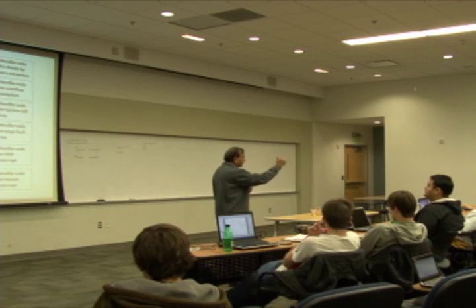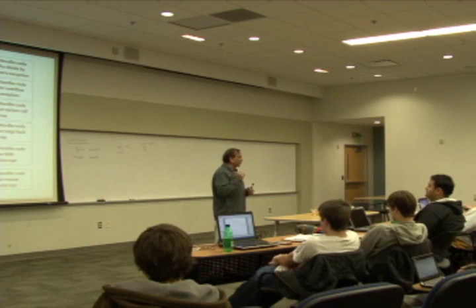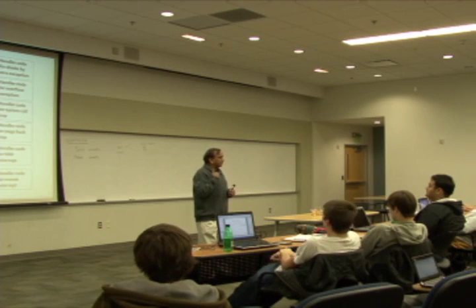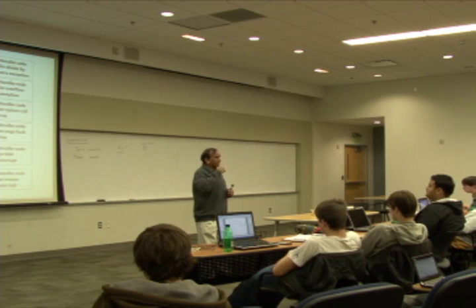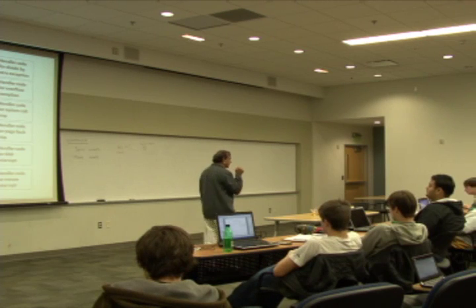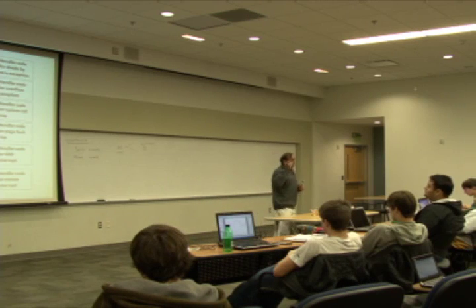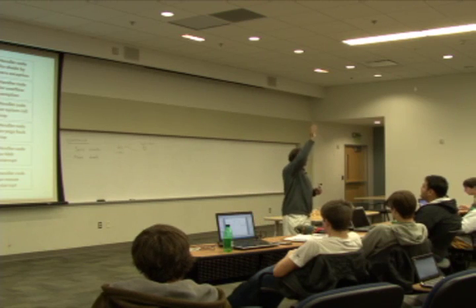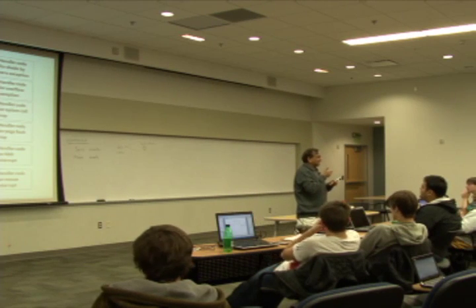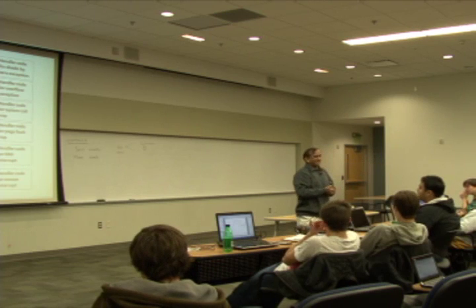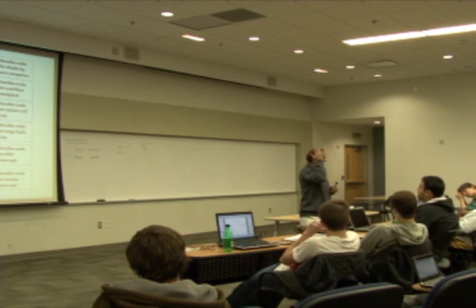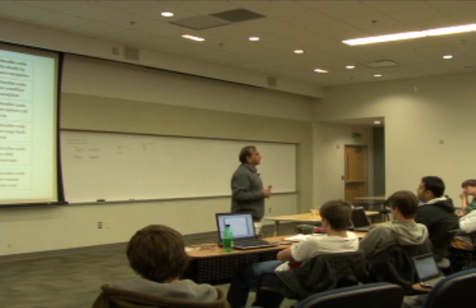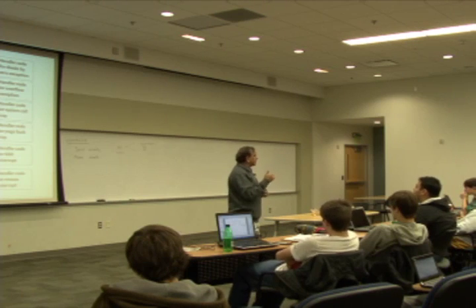And instead, if we decide to take the interrupt at well-defined points, even though it is happening at any time, the processor has the ability to decide when to take that interrupt. It's sort of like I'm lecturing and Shane puts up a hand. I can immediately stop my sentence halfway and then see what she has to say. Now that will mess me up completely. So instead I might say, well, I'm going to finish my thought before I take that question. And so that is the same thing that the processor is doing.